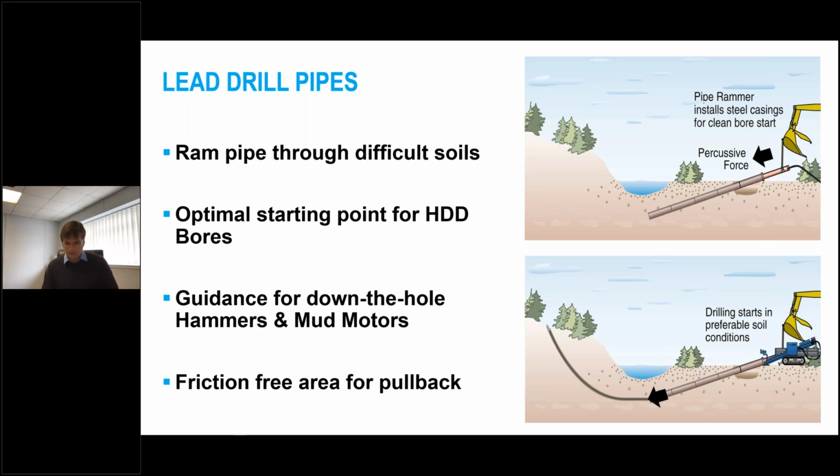and sand is notoriously difficult to drill, as we know. So these conductor barrels are installed until we hit more drillable soil conditions, and it makes for easy lead-in, either for your standard drill head or for down the hole hammers or mud motors.